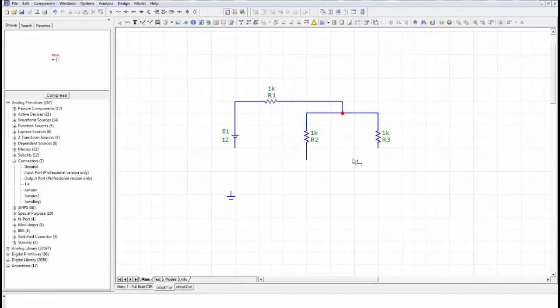Down here, left click across, move up, let go, left click again, and then finally I would like some more wiring from the bottom of the battery, move across, let go, left click again, push that wire into there, hit the selector tool, and I'm going to then have the earth pushed into there, and that don't look too bad.